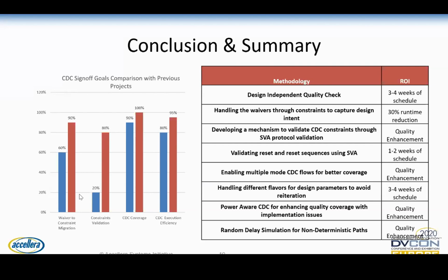As I said, earlier we only had a single mode of operation for CDC analysis. Now we ensured that wherever there were multiple modes of operation, be it functional, DFD, TAP, VISA, anything, we have ensured that CDC is run for those modes, and the sign off is done with those modes of operation as well.